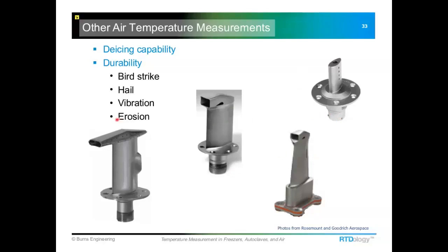And then this probe here is one that is used on a test boom that would go on an experimental aircraft, and so they'll have a boom sticking way out in front of the nose of the aircraft, and it would be in the very clean airflow, and it has an exposed platinum wire doing the temperature measuring. So it's very fragile. Lifetime is usually measured in hours, but they need the quick response of that type of sensor in those situations.